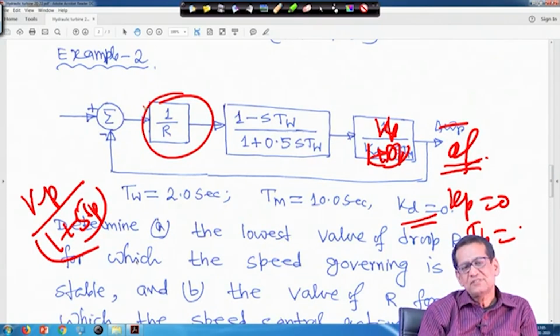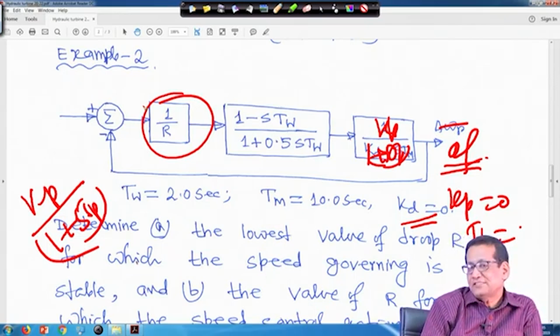That is why, for theoretical or academic interest, if you take the transfer function of the governor and see the responses, it takes more time to settle because of its time constant, right. It takes more time to settle compared to a steam turbine. And when you use an interconnected system, where one area is a thermal system and another area is a hydro system, because of this effect you will find it takes longer time to settle, right. So, these are some general ideas.